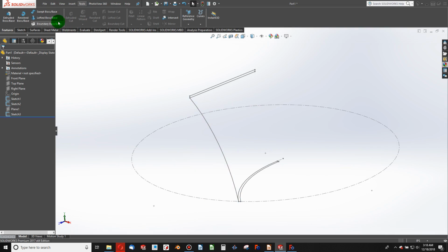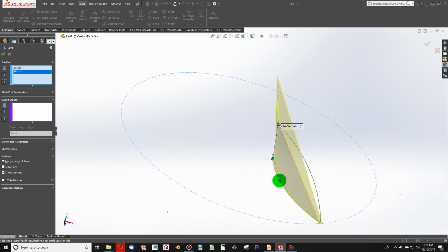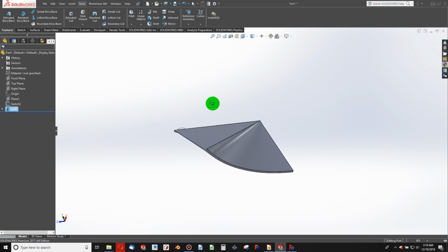So what I'm going to do instead is go to a loft. And loft gives me a profile, so I can go here and here. And here's a little alignment tool that SolidWorks gives me. You know, when I move this to the other side, now the path is actually crossing over itself. It wouldn't actually work in being a solid. Oh, apparently it would.